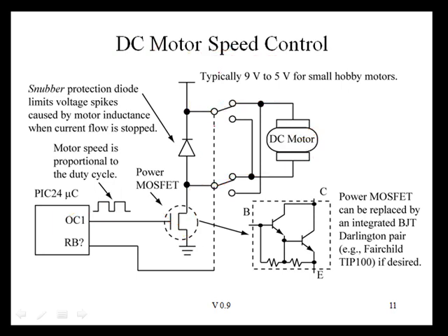What about this other set of switches here? What are they for? Well, let's put this switch in this other configuration. We'll put it there, and we'll put this switch there. Now let's trace a current path from VDD. We're going to trace through here, through there, back around through here, and to the MOSFET. What's going to happen is this will reverse the current flow. When we reverse the current flow through these switches, the motor will spin in the opposite direction.